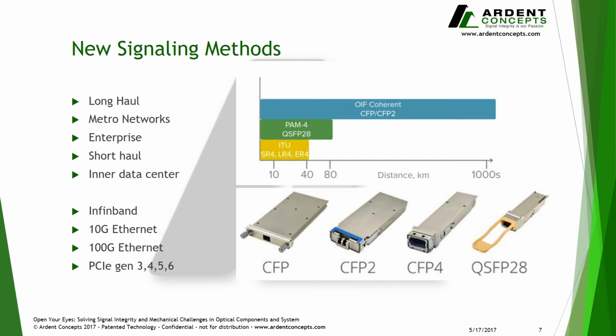And obviously, you need to start having integrated coherent receivers in devices such as the CFP modules to start understanding what's going back and forth between the data transmission. Unlike a QSFP module, where arguably the TOSAs and ROSAs are relatively passive, with the transmit and receive ends of cable assemblies like a CFP2 module, there has to be some built-in intelligence. That's where the coherent receivers come into play, understanding what modulation scheme is being sent across and how to decode it. This results in increased data rates as well as increased data rates over transmission distance.